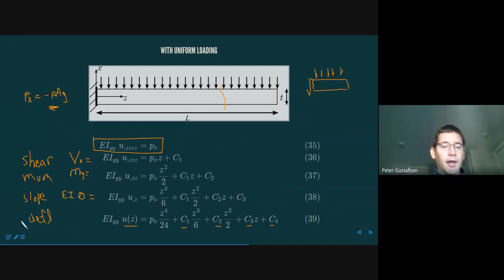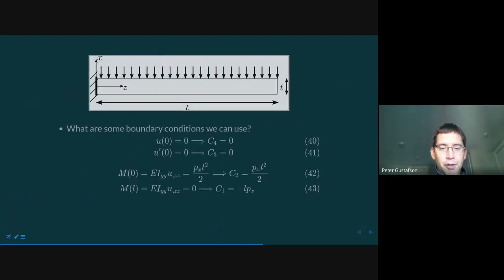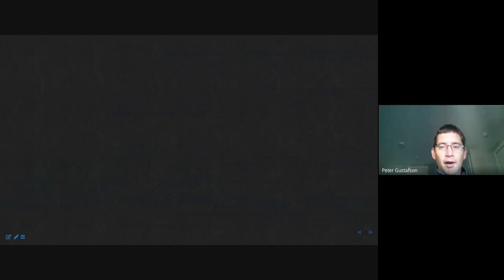We did a deflection one. We did a slope one. Actually, I'm going to pull two moment equations as my remaining boundary conditions. So that's what, it's probably flashed on your screen a couple of times already. The first one is really the one that's written last. That's the moment at the end. Okay, so the moment at L, I chose to be equal to 0 by observation. And that, again, would take us back to the idea that we went through on the blackboard.